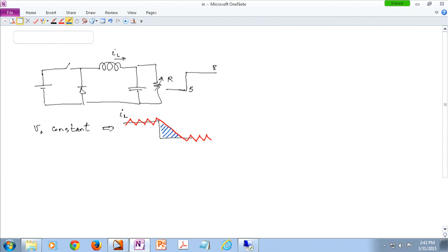So this difference between these two areas, the capacitor actually sees the difference between these two, and it is integrating the difference between these two. So you always have a dip or overshoot in your output voltage, okay? So that is very natural. Do not try to eliminate it. But then the system recovers a little bit quicker this time, okay?